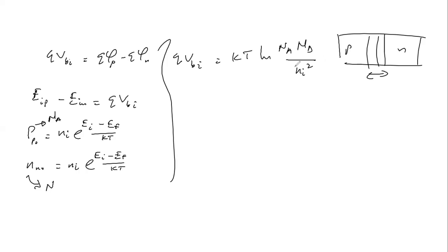So once we forward bias this device, this is the p-type, so we are going to apply the positive potential here, and here we're going to apply the negative potential. So this is forward bias. It means this is going to repel all the negative charges, and so the depletion region will reduce for net flow.